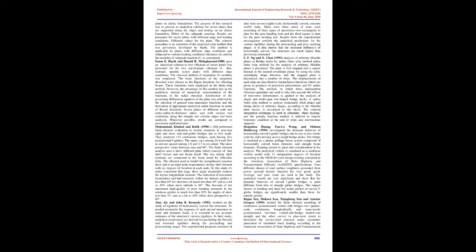The finite element analysis uses a skew-stiffened plate which consists of thin shell elements and one beam element. The two thin shell elements are connected to the beam element by rigid links. The element used to model the reinforced concrete deck slab is an 8-node isoparametric thin shell element with 6 degrees of freedom at each node.